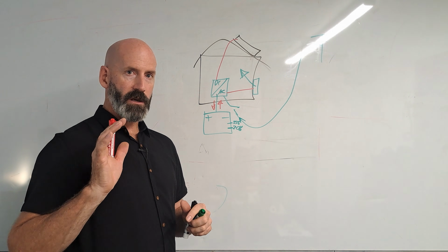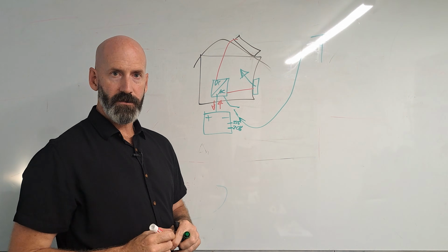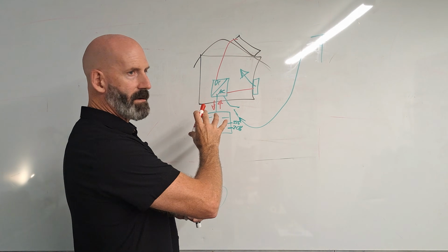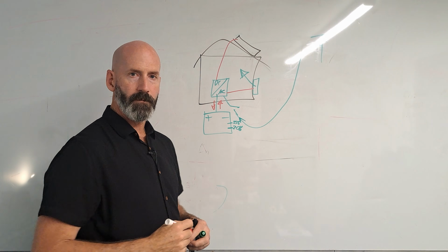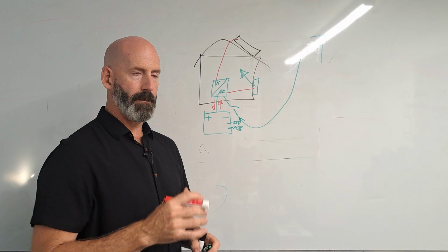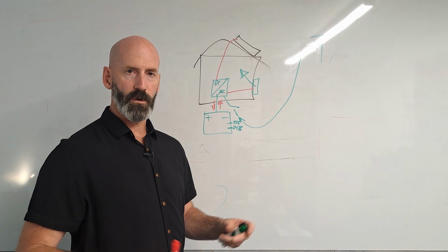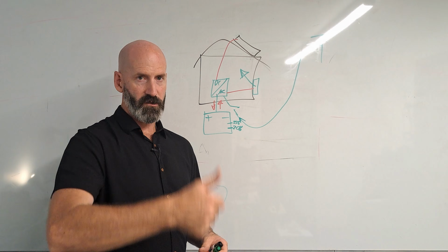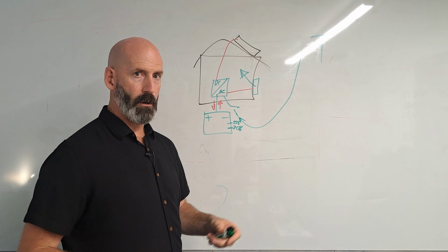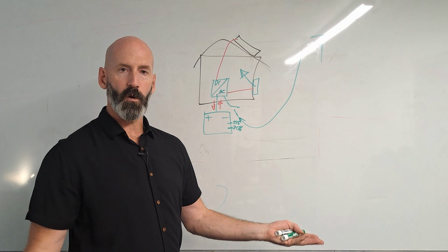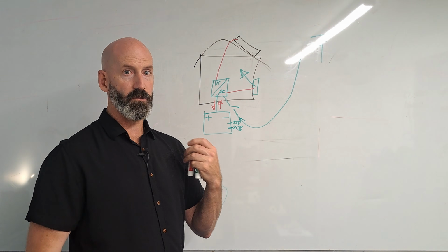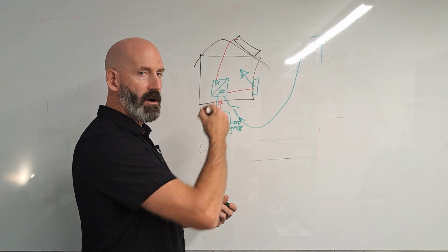One, if you get brownouts on your power lines, that's not going to affect your system. It will affect you in a hybrid system. One of the reasons it affects you is because the grid, that main power supply that is not your system, in both off-grid and in hybrid, becomes the controlling voltage and frequency for your system. So if this starts to spike with the voltage, or it starts to drop the frequency or drop the voltage for a brownout, your whole system will match it until it falls out of parameter. It will probably shut down for a second, disconnect and start itself again. So you'll still get some issues with brownouts with a hybrid system.